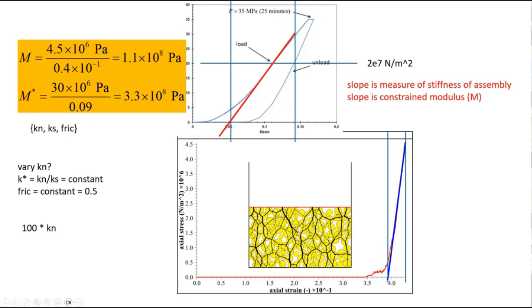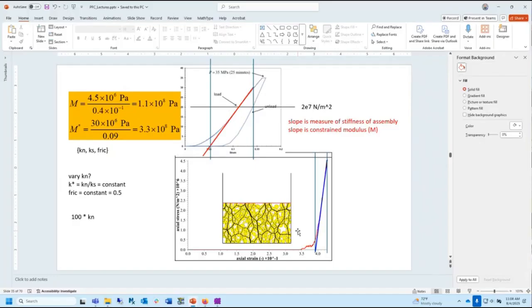You could see that when you ran it. You could see the force change. Nothing is changing. There's no new contacts forming. So I want you to measure the coordination number during the run, and I want you to make a history of coordination number versus axial strain. If that hypothesis is right, we make those plots right above each other.